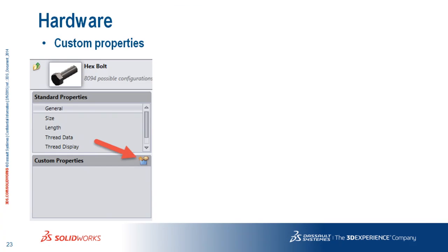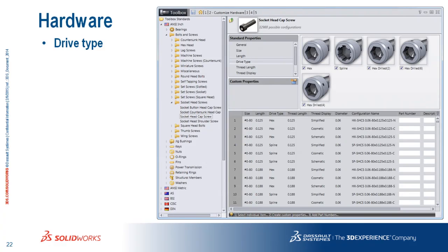This one right by itself has 32,988 possible configurations, okay? But they're not all loaded yet. It only creates those as you insert the part. So when you use a part, you insert it, it creates the configuration on drop of that component, okay? So these are possible configurations. They're not necessarily loaded into the part ready to go, okay?